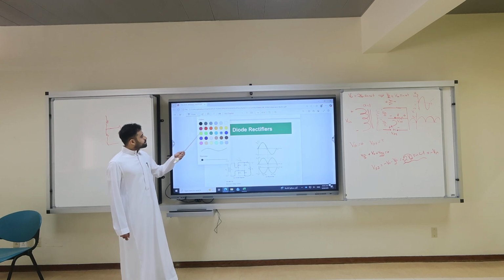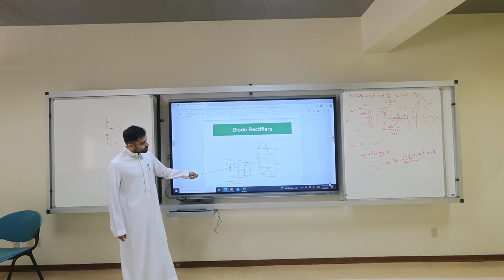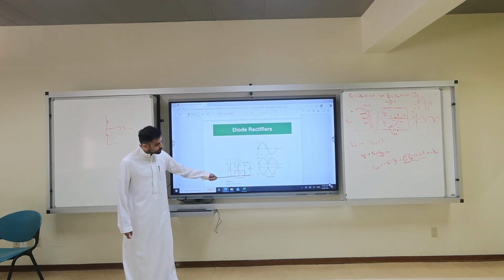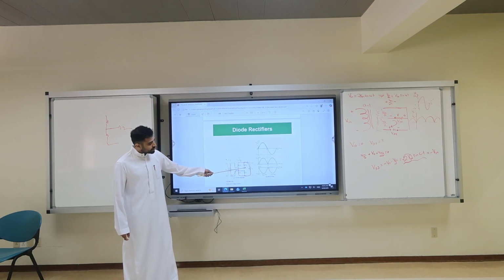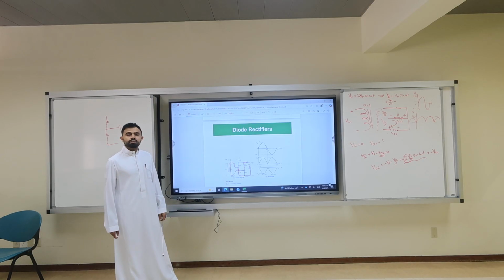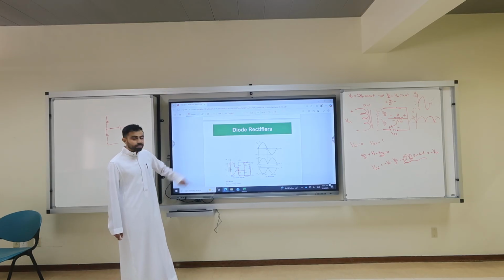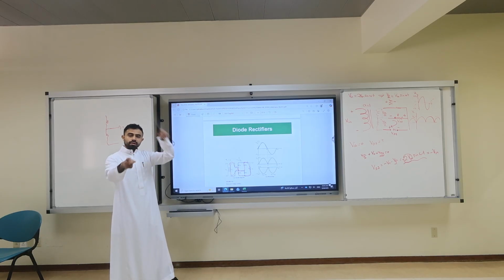For a negative cycle, D4 is on, D3 is on. Why? Because D1 will be open circuit and D2 will be open circuit. D3 and D4 will be short circuit. They are reversed.